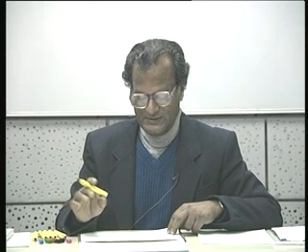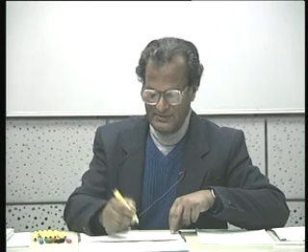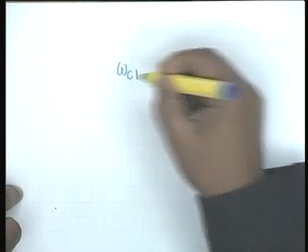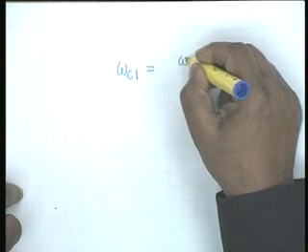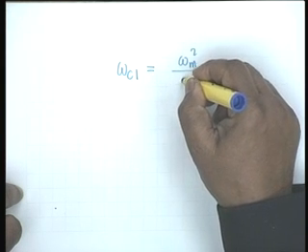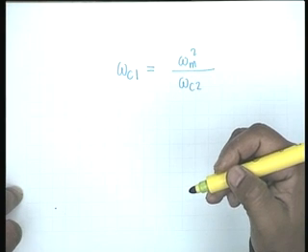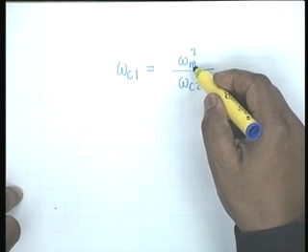Okay? It is a fuzzy logic, it is not very clear as to why we cannot find out, and that is why I throw you a challenge. So what you said? Omega c1 may or may not exist. If it exists, then it can be shown, and that is not too difficult, I also leave that as a challenge. If omega c1 exists, then one can show that omega c1 is equal to omega m squared divided by omega c2, which is obviously lower than omega m. Agreed?